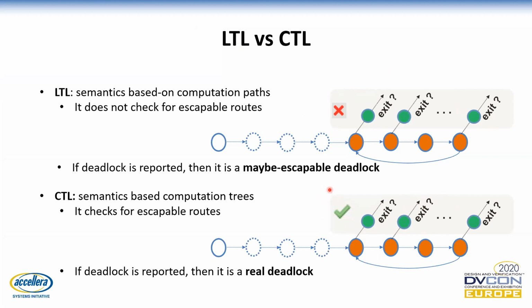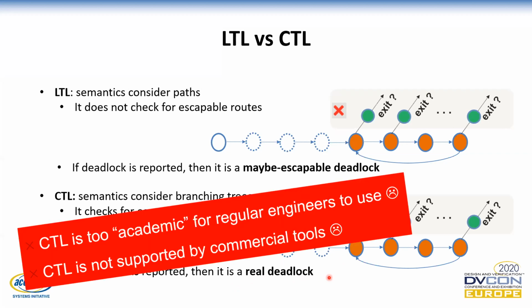This is the case for CTL. So with CTL there is an obligation for the tool to do so, which is what we are looking for. It means when the tool tells us there is a deadlock, then this is a real deadlock. So CTL looks like a good candidate. The problem is that CTL is too academic for regular engineers. It is not supported much, or not supported at all, by commercial tools.